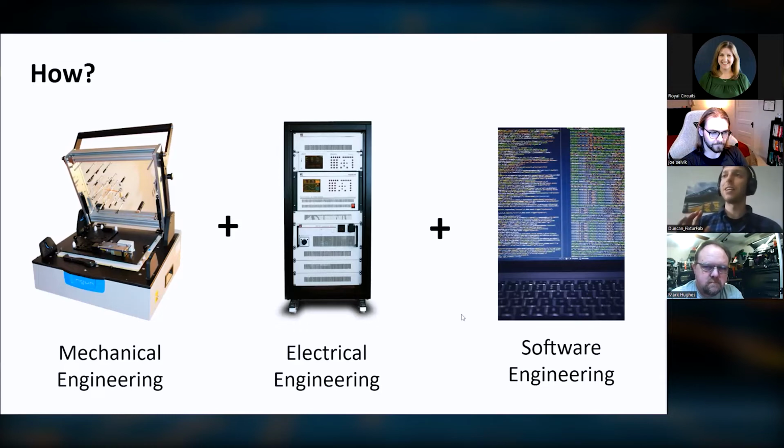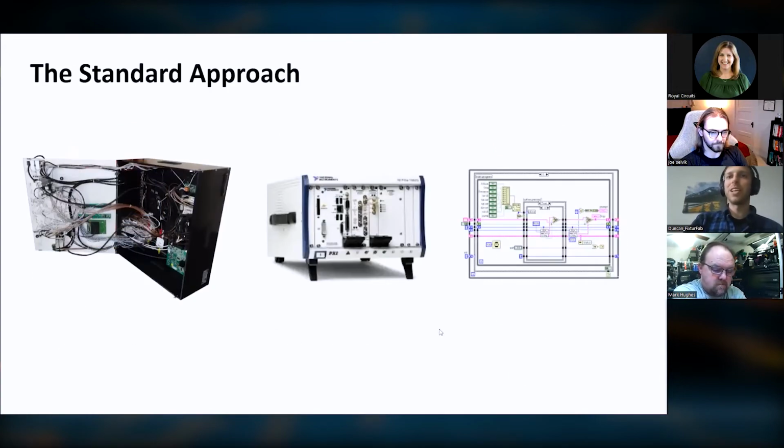And then to tie it all together, there's a lot of software engineering involved because you need to develop an automated test plan that will run these tests reliably throughout the manufacturing day. The standard approach for this is test fixtures, which have been around since the 70s. It's been around for a long time. But the typical way to go about this right now is to manually wire your instrumentation to the bed of nails fixture. You can see this on the left-hand side, just wires everywhere.